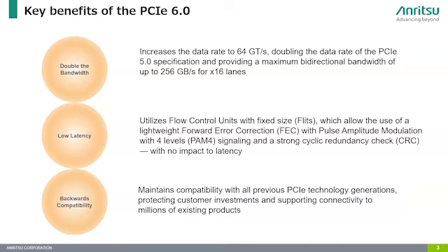Then low latency is the key of PCIe. Utilizing the FLIT control unit with the flits, and a light forward error correction, and using PAM4, it achieves double the bandwidth but still very low latency. The third one is backward compatibility. Even with PAM4 in PCIe Generation 6, it's always backward compatible with PCIe 1 through 5.